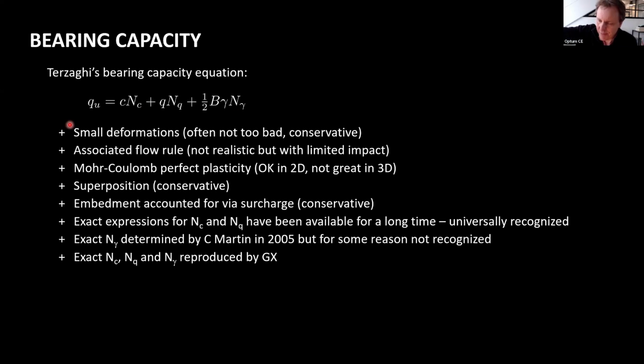If you have a foundation that you really press into the ground, then of course you generate surcharge, you generate a Q term, you generate some embedment, so that changes the bearing capacity. And if you reach that new capacity, you generate more embedment and so on. So it is a simplification that sometimes holds, sometimes not so much. Associated flow rule, that's something that's been talked a lot about. That's of course not realistic, that we have as much dilation as friction, but it does not have too huge an impact at the end of the day, especially not compared to the first one here, and also various other effects.